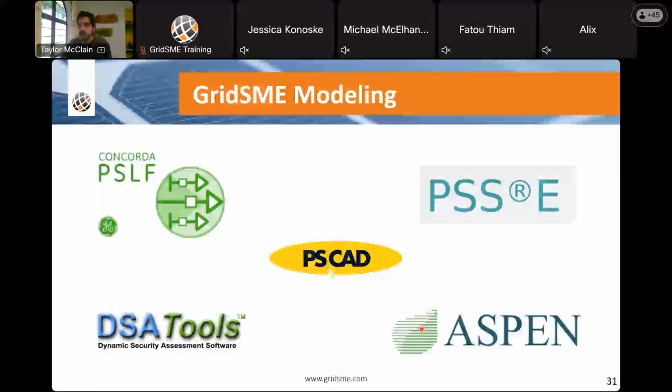You might see full system models where they've actually gone and modeled every single inverter, every single piece of collector system, every single pad mount transformer. But for the purposes of these interconnection request level submissions that we're doing, everything needs to be tested on a larger scale, on a full system scale. And so we see that the equivalent modeling is used in all of these tools to aid in the ability of accurately testing these without overdoing it on the equipment that's modeled.